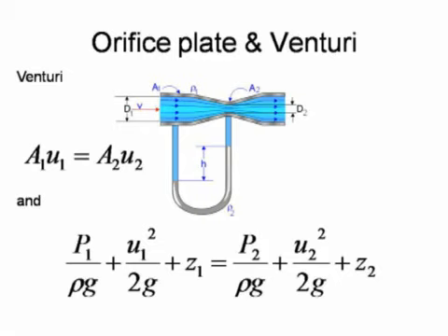And then the equation at the bottom there is Bernoulli's equation in terms of energy per unit weight, because we've divided through by g. In fact, that equates to simply measuring terms in terms of their head. So the first term is the pressure head, the second term is the velocity head, clearly fairly similar to half mv squared, or half times velocity squared. The third term on the left is the height above the datum, and then on the right hand side we have again the pressure head, the velocity head, and then the potential head.